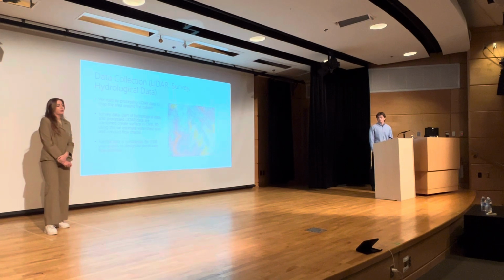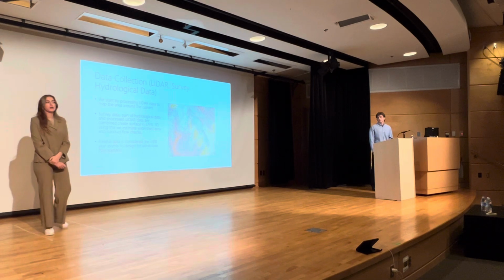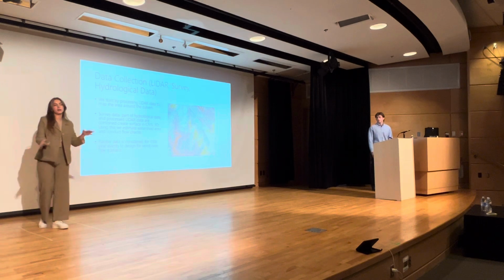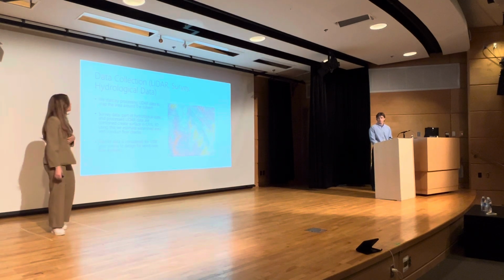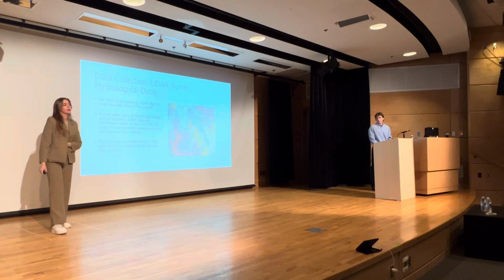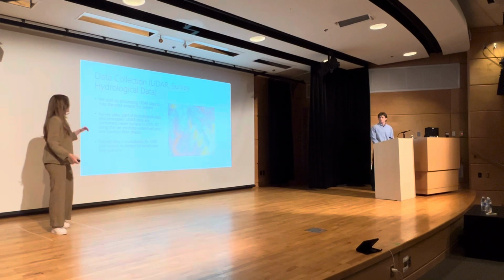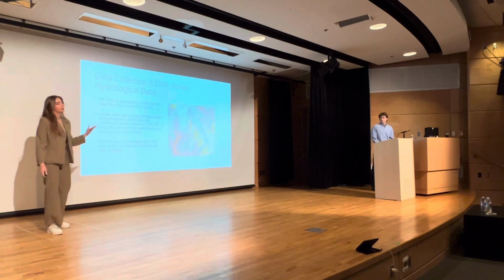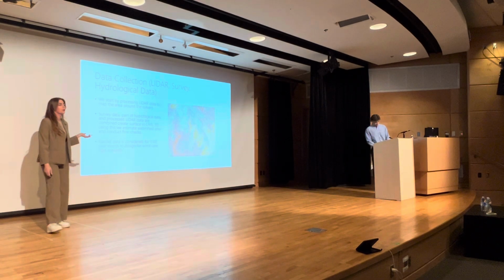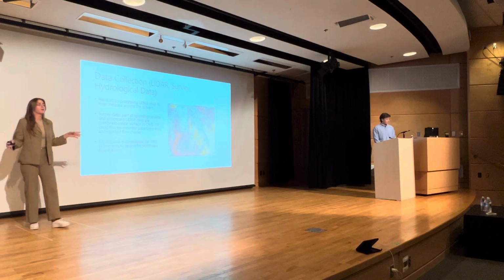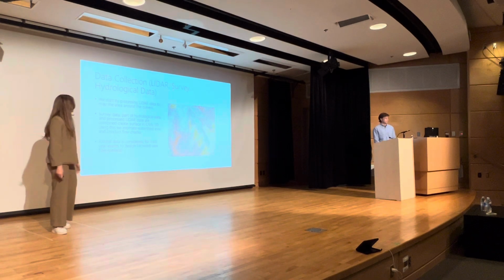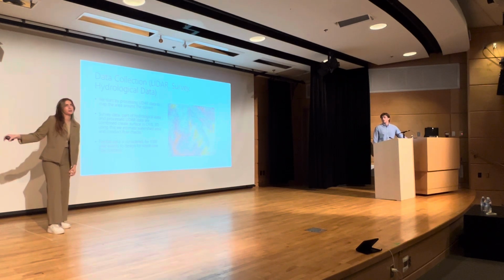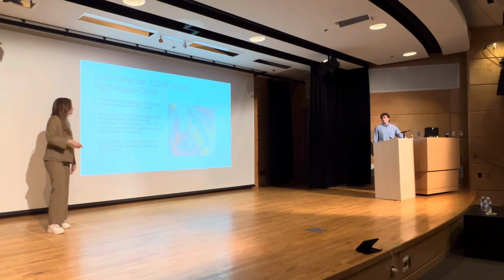After that, we need to add the hydrological data. When we talk about hydrological data, we can consider a few things. It'll be the watersheds, water paths, so basically all the water bodies that are in the site, or it can be rainfall data. The data that we will be collecting and downloading will be the water bodies around the site. I input that into Civil 3D also to help us with our watershed, which is the area of the water that will flow through the culvert. And the water path is the path from the beginning of the watershed till the culvert.